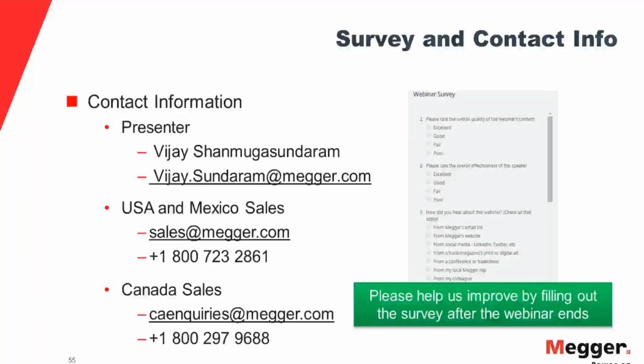Having said that, there are many factors which affect the normal operation of your differential function. We talked about most of these. You have CT mismatch, you have CT saturation, you have switching currents, magnetizing inrush currents, the overexcitation condition, or your zero sequence components. Having said that, we do offer different ideas for different challenges, and try to overcome those challenges in the field.